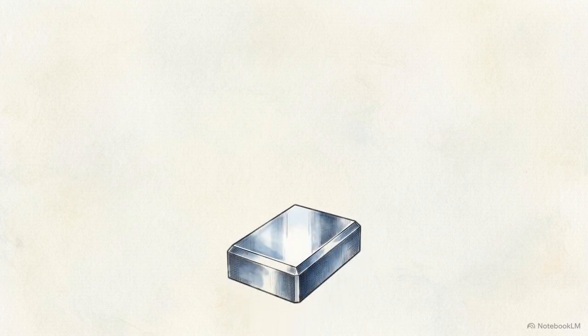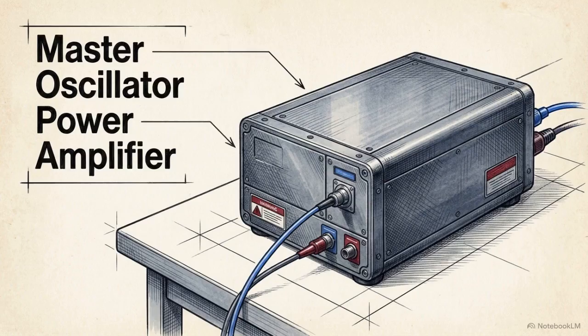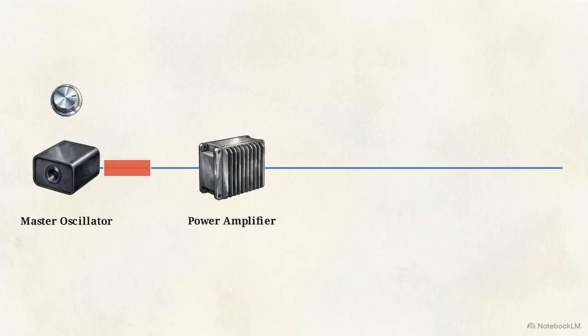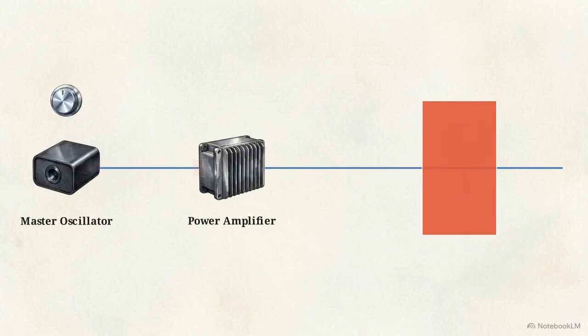Metals present the opposite challenge. They reflect the mid-infrared radiation of CO2 lasers, but absorb the near-infrared wavelengths generated by solid-state and fiber systems. The MOPA fiber architecture offers a level of control that standard metal markers cannot match. By separating the seed pulse from the amplifier, MOPA systems allow the operator to adjust the duration of each pulse independently from the total power output.